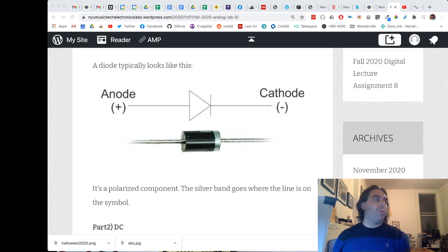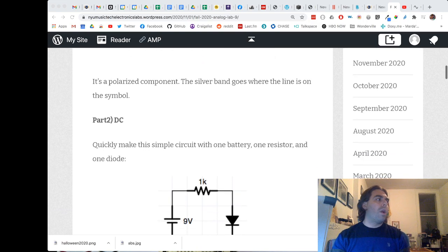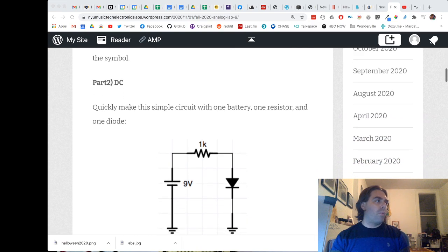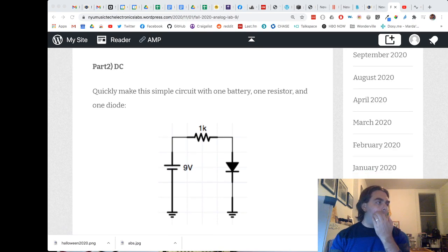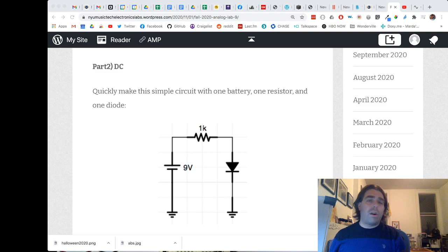Diode clipping is only one of the ways to create distortion. And so we can use this extremely simple circuit to create distortion, fuzz, overdrive, all of the different varieties of distortion that exist. So first, let's look at something here. We're going to do a quick test using one battery, one resistor, and one diode. So I am going to use a 1K resistor and my diode and one battery. I'm going to still use my same battery harness, but I'm just going to leave the -9 unconnected.